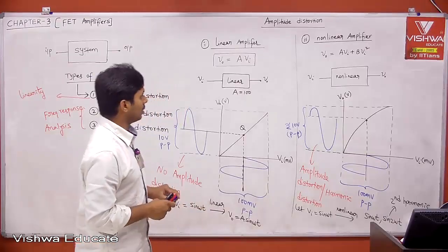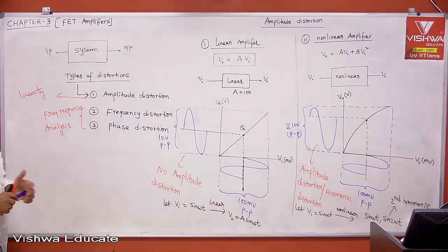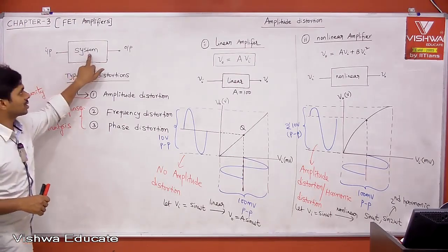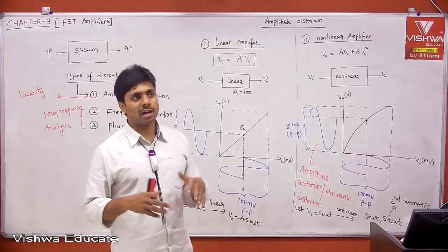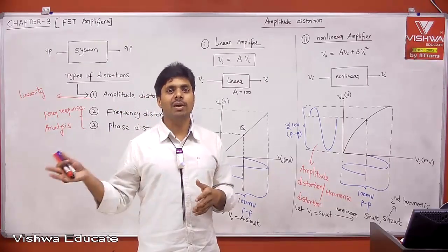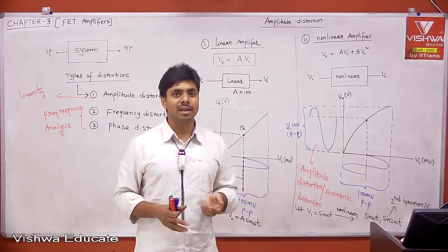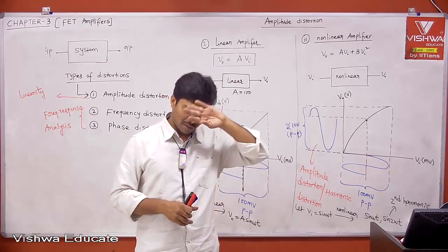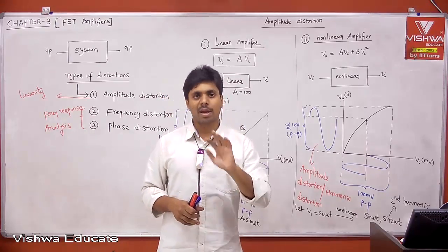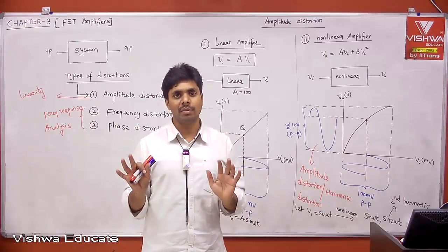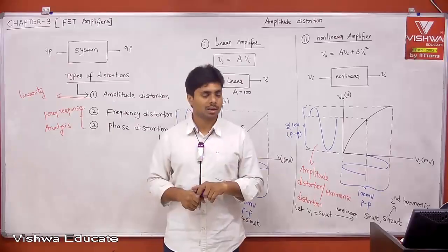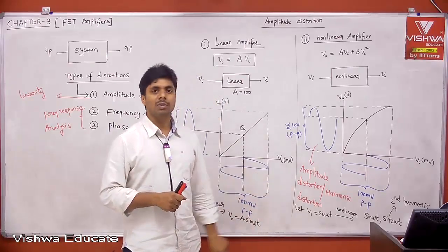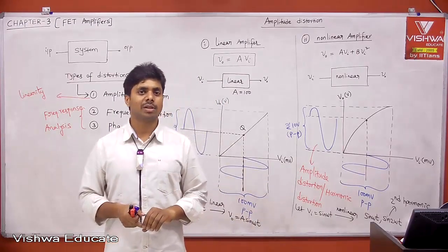But practically, whether the system is linear or not, that is what we need to consider. That is the reason why in signals and systems and control systems, the system is always linear. We always apply the techniques for linear time invariant systems. Time invariant is nothing but aging; with respect to time the system parameters change, but practically people assume the parameters are not changing. The system is time invariant and linear. That is compulsory. If the system is not linear, we will get harmonic distortion and the superposition principle is not valid.